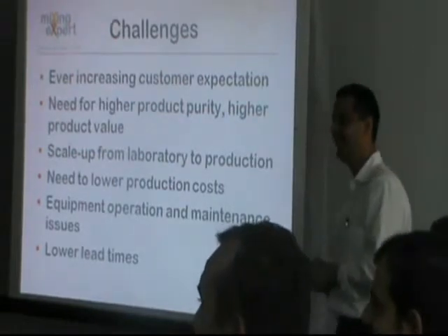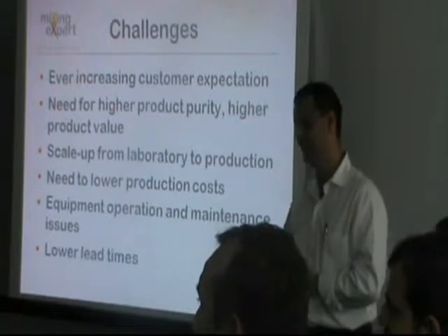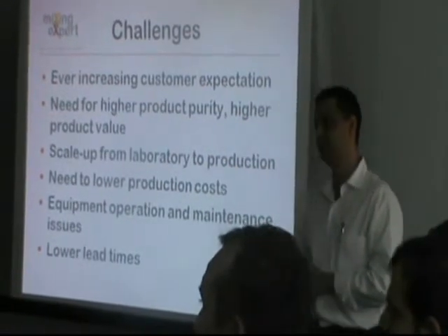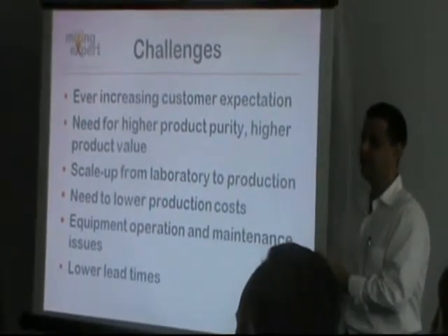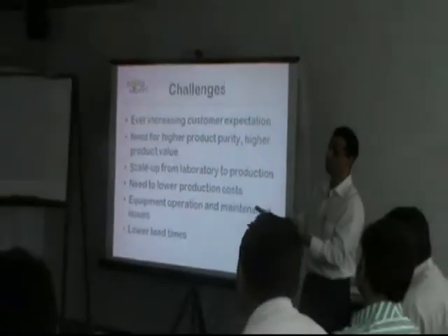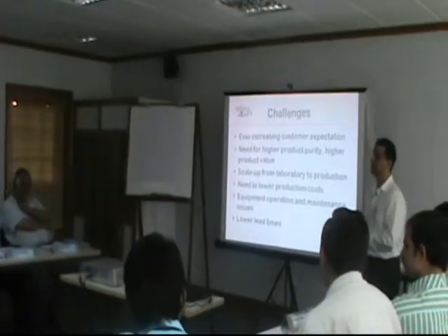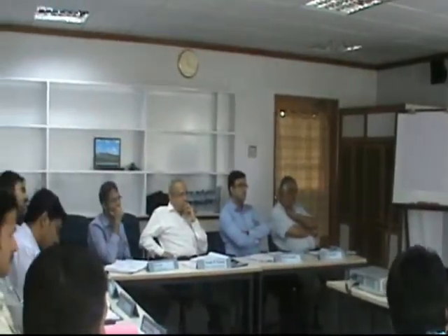When we increase the speed, the power consumption increases. Then should we judge it from the amperes or from the kilowatt hour? See, in most cases, most plants have an ampere meter. That's the most common thing. So the motor amperage is a good measure of the power drawn.